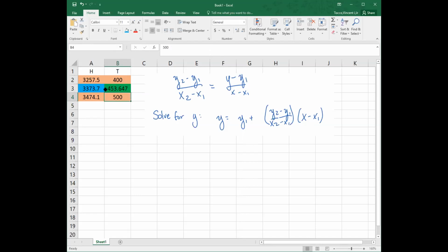So you can use this formula for any interpolation that you have to do. All you have to remember is to replace the orange cells with data points that you know, replace the blue cell with the data point that you want to find out about, and then this calculator will automatically calculate what your temperature is. So this tells us that T2 in the Joule-Thomson example is less than T1, which perhaps makes sense because, again, pressure and temperature go together. So if pressure decreases, temperature will also decrease. But as we'll see coming up, that's actually not always the case. So in the next video, I'm going to show you how you would calculate this using Unisim software.